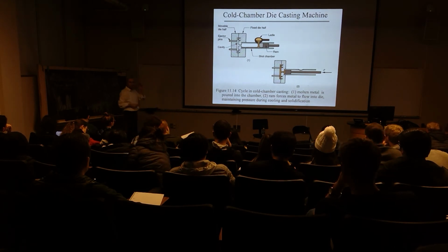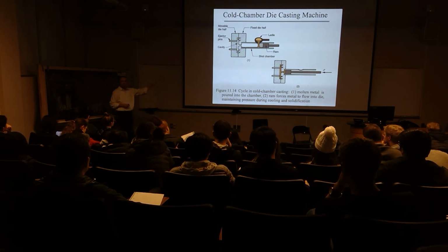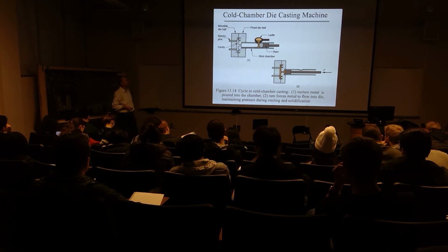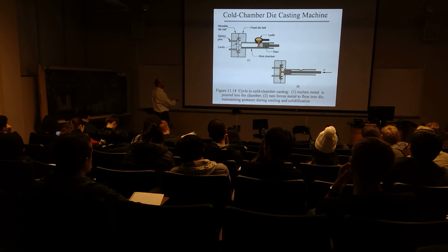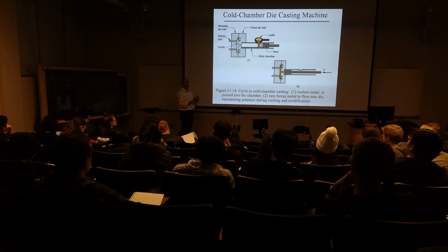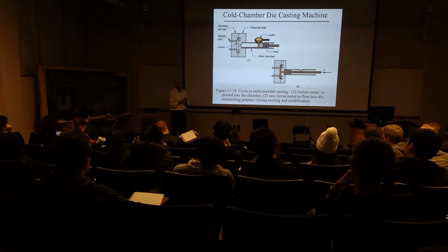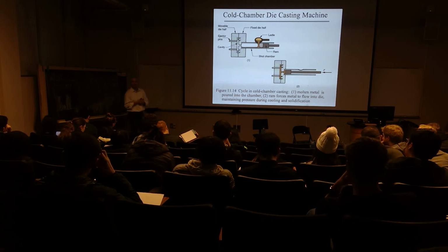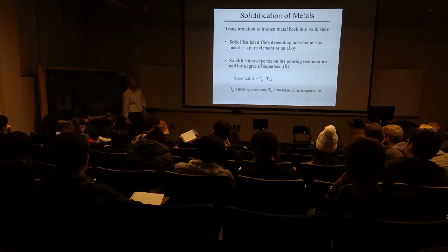Okay? So, temperatures are important to whether this is expendable or non-expendable. And then also, to some extent, surface finishes, because in this case, your metal is contacting a metal mold that has very well-defined surface roughness, high quality, low roughness, whereas in the other case, our metal is touching, of course, sand. And you've made sand castings, so you know what that surface looks like.